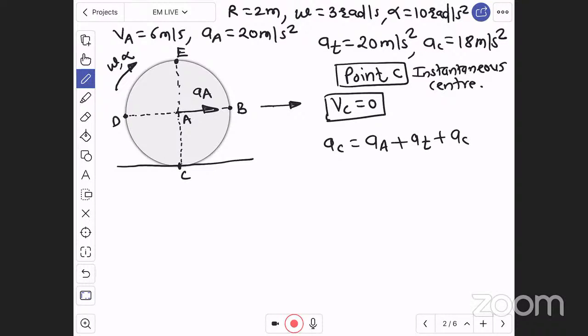All this will come at x. See my dear students, AC is the acceleration of C point, and here, instead of this AC, I will write AR, so that you will get a clear idea. Radial acceleration, here you have to make the correction, AR. It is not really a correction, we also call it centripetal acceleration, right? But since point C has come, we do not want confusion in AC. AC is acceleration of C and AR is centripetal acceleration or radial acceleration, right, which is 18, right.